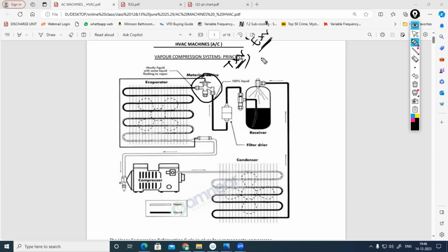if you are using a thermostatic expansion valve or electronic expansion valve, the rate of flow of refrigerant through the loop will vary. For example, the AC machine is 1 ton of refrigeration, meaning 3516 watts. The flow of refrigerant might be 1 liter per second. But the evaporator load is 0.5 ton of refrigeration, let's say 1750 watts of heat in the evaporator.